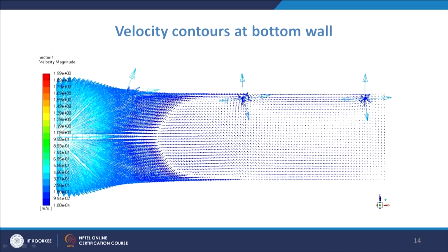You can also have the velocity at the bottom plane. As you see in the plan view, the liquid metal strikes the Tundish bottom, and then it is spreading in all the directions. So, we are having a very high velocity there. Then slowly the velocity will be changing, and you see that considerably large velocity is coming, and then you will have the metal coming through all these outlets. So, the velocity can be computed, and you can see where the velocity is high and where it is low. These ideas can be obtained from these velocity vectors that can be drawn.